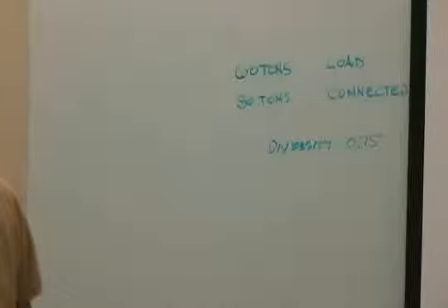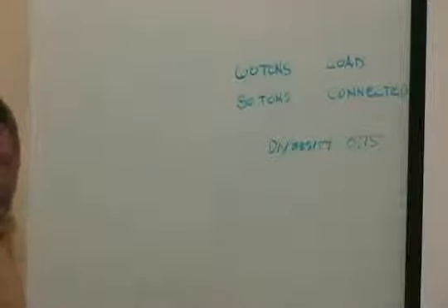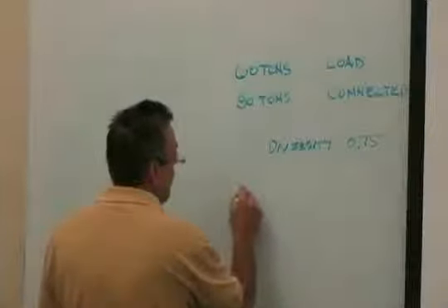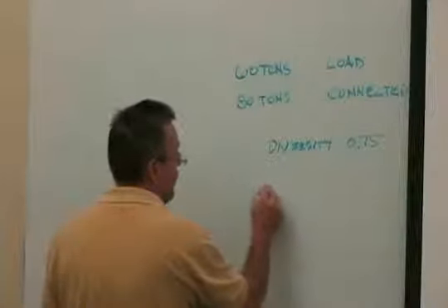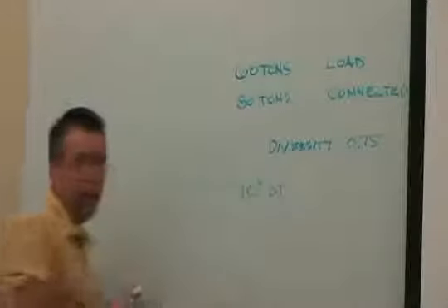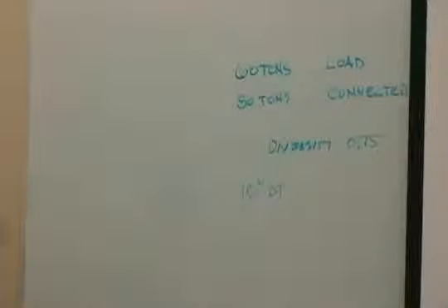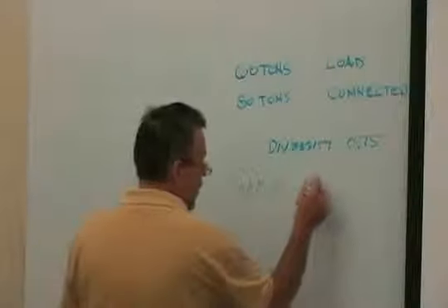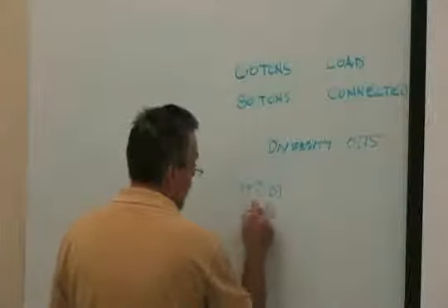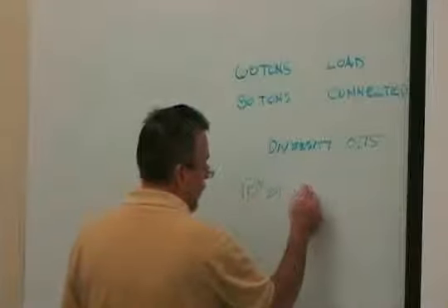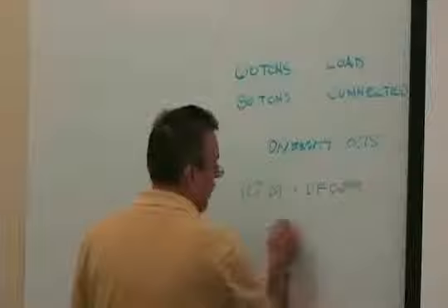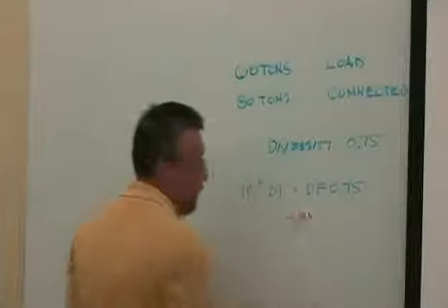And then diversity times delta T plus air and water. So take the diversity. I've got a size of my system on a delta T, 10 degrees. We talked about 90 degree into the fluid cooler and 100 degree out of the fluid cooler. So I've got a 10 degree delta T. If I take that times my diversity factor, which is 0.75, I actually end up with a 7.5 degree delta T.